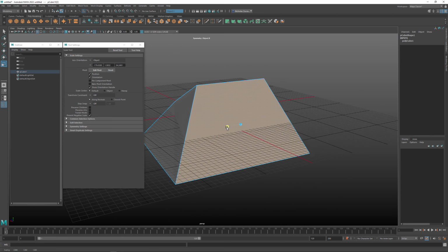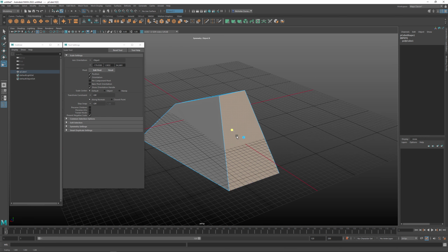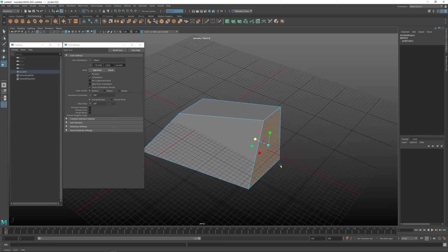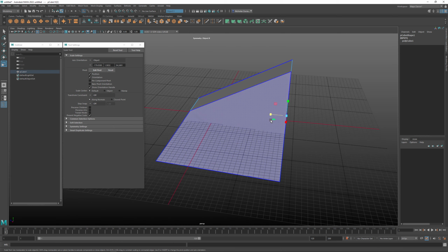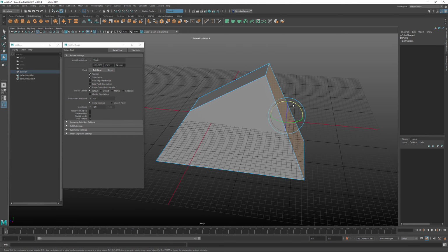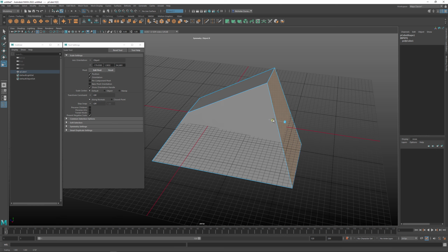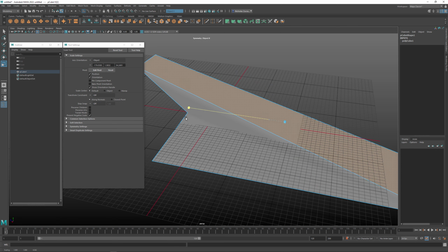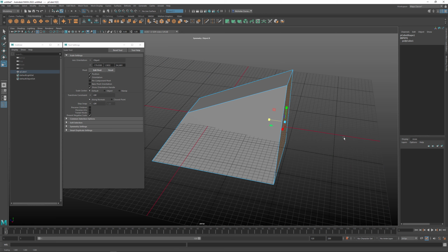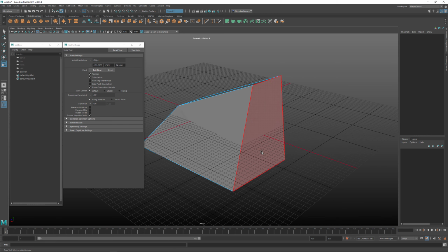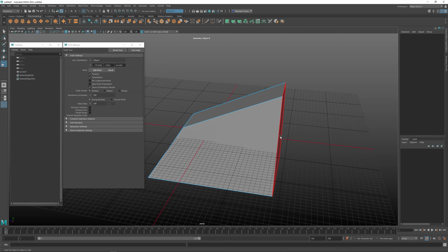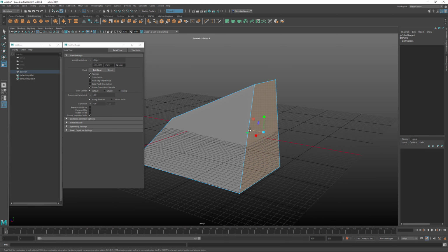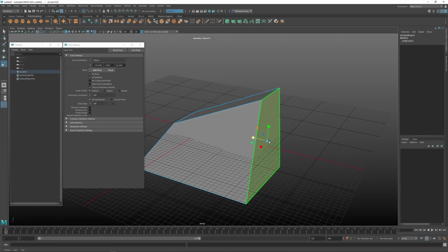So again, you can take the whole face and you can manipulate it using the different scale tools that we've got in here. So we can scale it in this dimension, and you just saw what happened whenever we scaled it that way. So something that's kind of interesting, I'm going to rotate it here. If we scale, you can see we can scale this way and it'll get really long, but if we scale here, it'll kind of hit a limit because everything kind of lines up, and then basically you've flattened out that face so it has nowhere else to kind of go. And if you take a flat face and you try to scale it out this direction, can't really go anywhere, right? Because it's completely flat at that point.